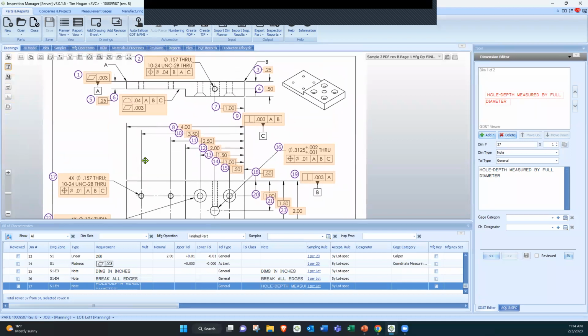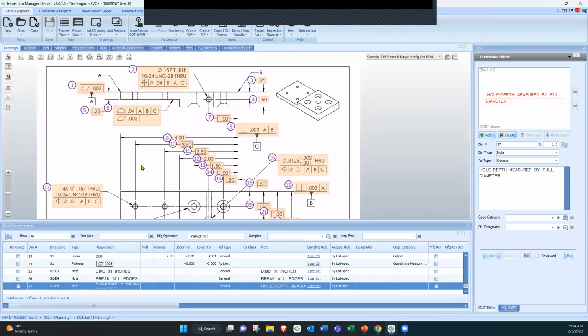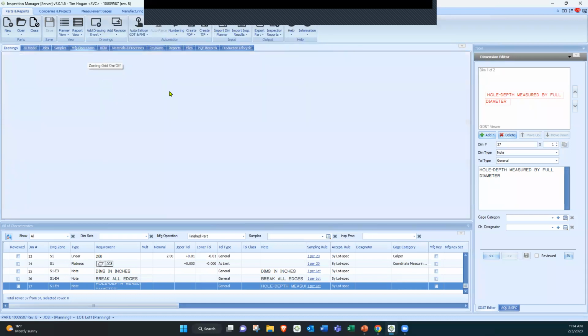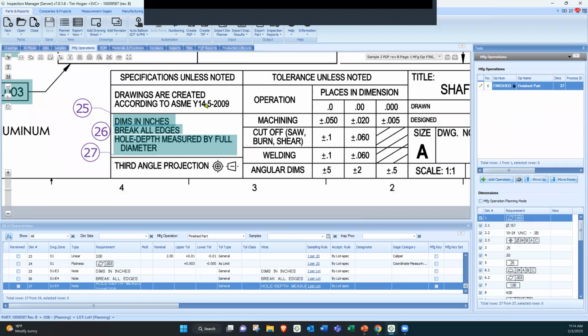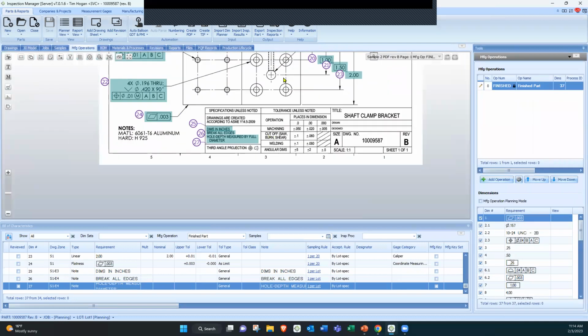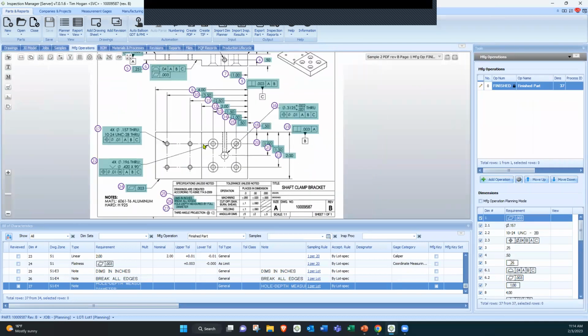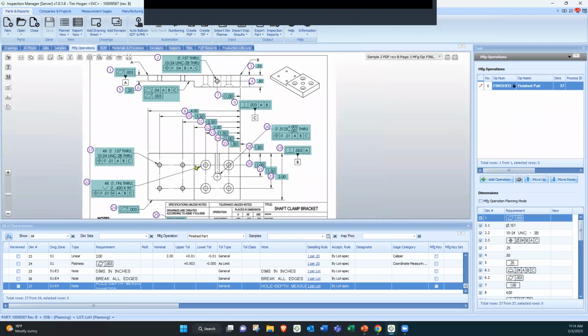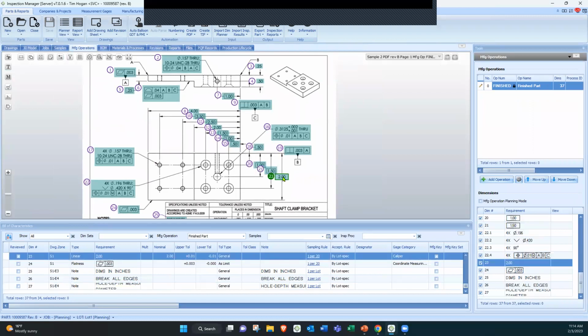So control plan information, I'm going to skip a lot of things that I normally skip because we're just focused on the control plan for today. Okay, but we are going to roll into manufacturing operations because that's a key component of building that control plan. All right, so in the manufacturing operations, we're going to break some of these dimensions out into specific operations because that's going to help separate our data on the control plan itself, right?